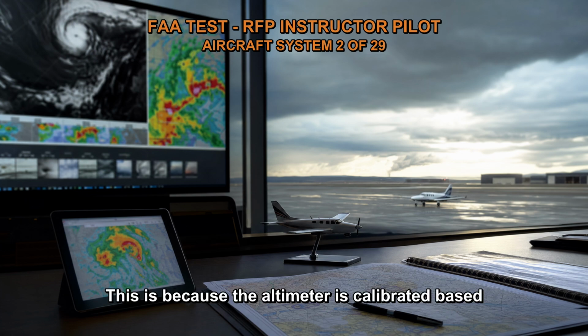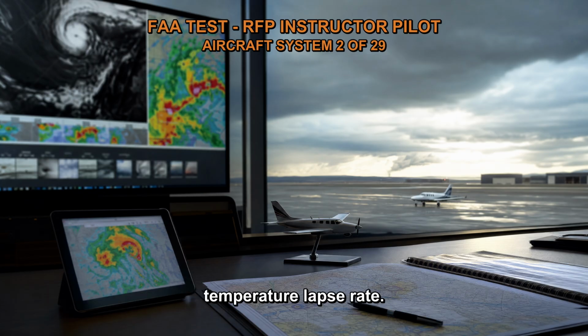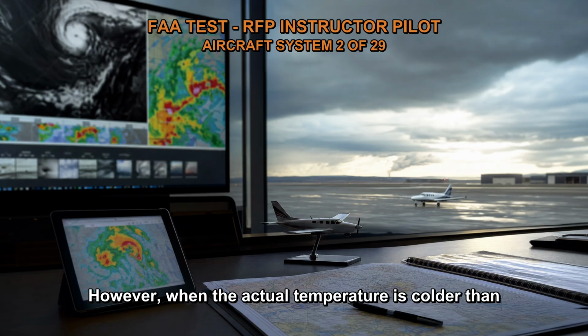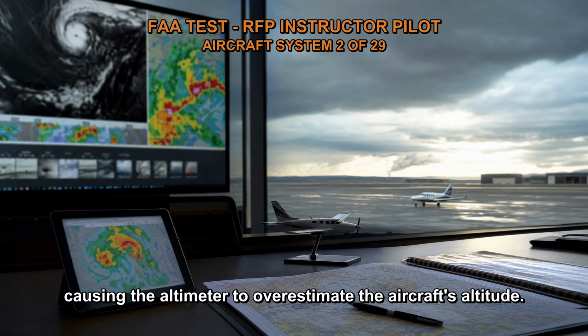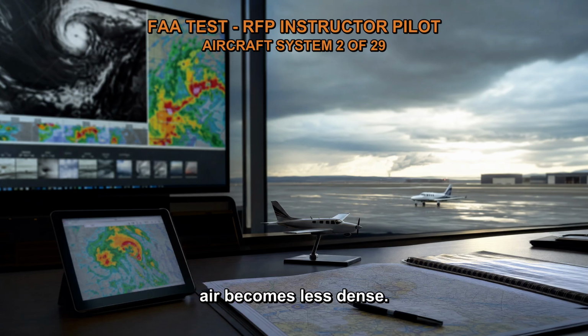the aircraft. This is because the altimeter is calibrated based on standard atmospheric conditions, which assume a standard temperature lapse rate. The standard temperature lapse rate is the rate at which temperature decreases with an increase in altitude. However, when the actual temperature is colder than standard, the temperature decrease with altitude is steeper, causing the altimeter to overestimate the aircraft's altitude. Conversely, when the temperature increases, warmer than standard temperatures, the air becomes less dense.